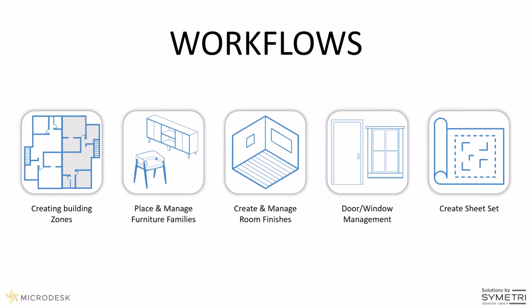We looked at creating our finishes, actual 3D floor, wall, and ceiling elements based off of our rooms, and then generating our room drawings from our rooms. We looked at our door and window management, being able to customize how doors and windows get numbered, being able to automate that just like we did with our furniture, so that every time a room number changes, the door numbers get updated, and then creating our door legend drawings.